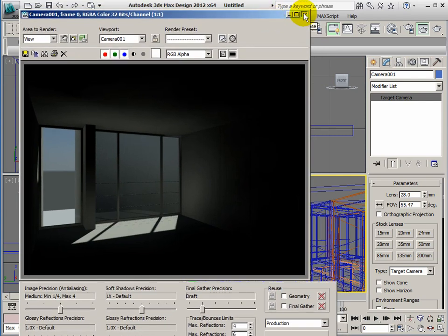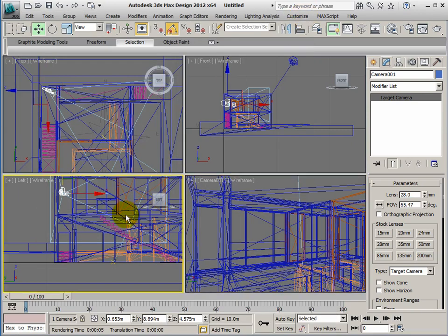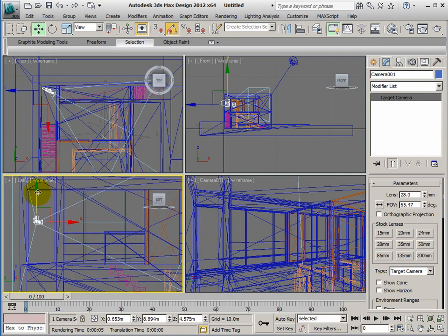Okay, and the first thing we'll do is add a light portal, which will help push the light into the room. Now ideally we would put two here, one there and one there, because each of these could then be controlled independently. But I'm just going to be lazy and put one across the two windows. I can see that window shape here: there's the tall window and there's the triple window.